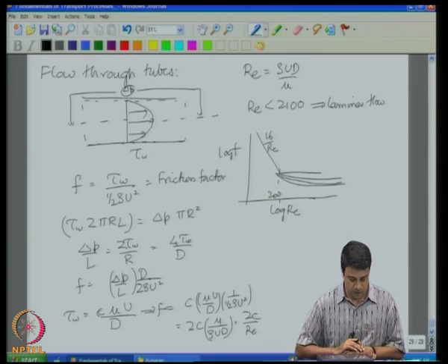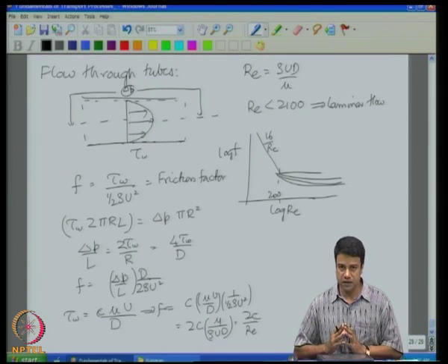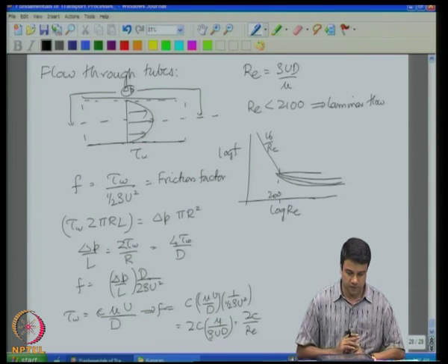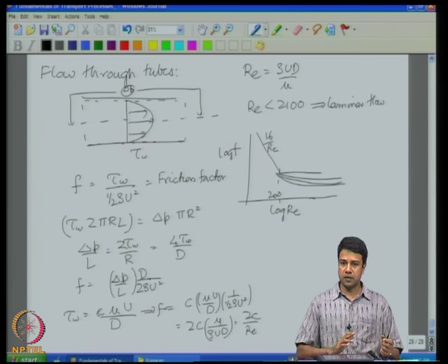So, we have completed our dimensional analysis part of the problem. Basically, the takeaway from this section is that you can do simple dimensional analysis, or you can do a more sophisticated dimensional analysis based upon what are the dominant forces in the system. In all cases, in heat, mass and momentum transfer, we are interested in predicting the average transport rate, which is an extensive quantity that depends on the system size, or the average flux, which is the transport of that quantity per unit area per unit time.